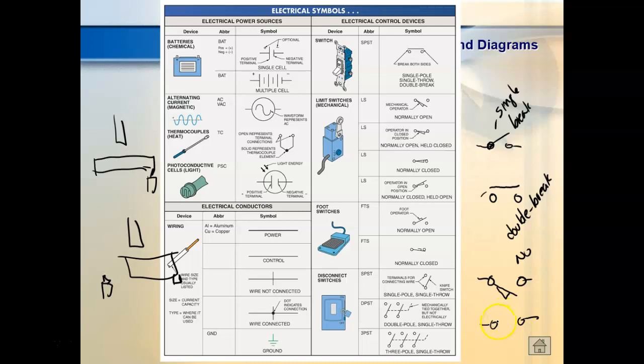So this is actually a normally closed contact. I didn't touch it. It's got a touch. So gravity is trying to close this one, so it's closed. Now, why we have different symbols is we're going to stop this piece of equipment and it's sitting like this, and that's its normal position. That's where it's sitting every day when I come into work, right? You understand? Well, even though this is a normally open contact, in the machine's normal position, that contact would be held closed. So that's why on limit switches we have two more symbols.